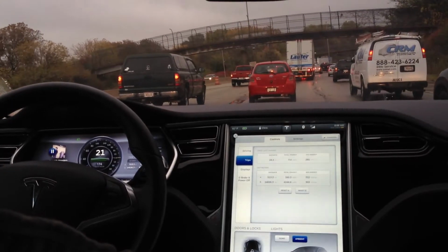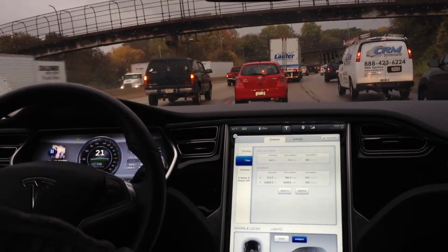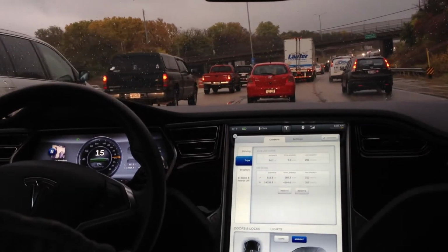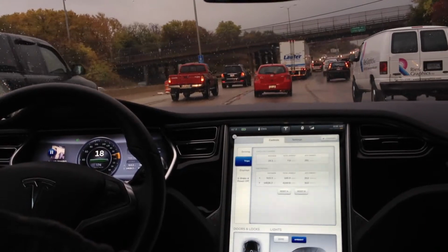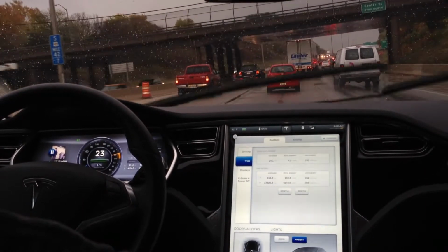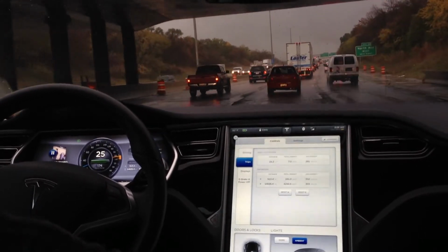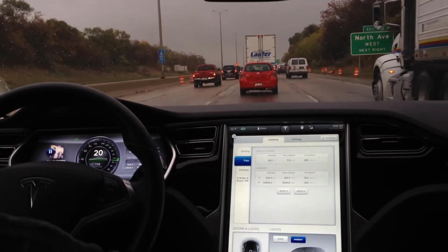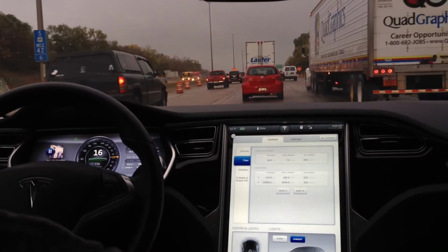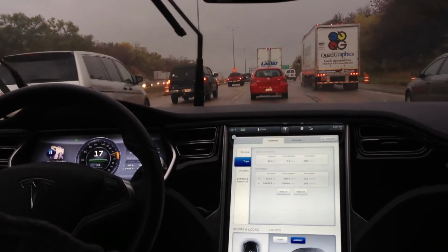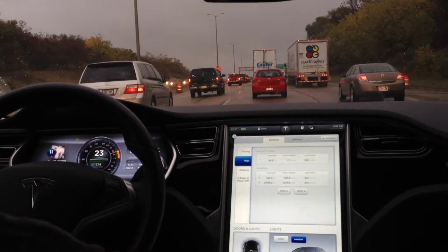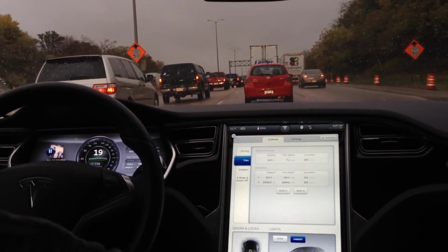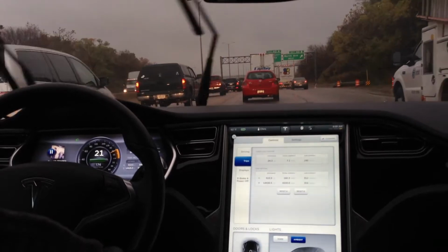Obviously, an electric car has got to be variable because you are varying your speed. It's not like a toaster where you hit the button and that's it. It turns on, gets hot, stays hot, and then shuts off. The electric car has to be able to do 0, 1, 2, 3, 20, 30, 40, 100, 110, 120, 130 miles per hour. If it just turned itself on, it would just keep going and going until the vehicle either hit something, ran out of power, or the motor self-destructs due to the RPMs. So your power usage varies. Right now, I'm drawing about 20 kilowatts, dropping down to regenerating 15 kilowatts. You can see how that regenerative braking can come in handy. I haven't had to touch the brake.